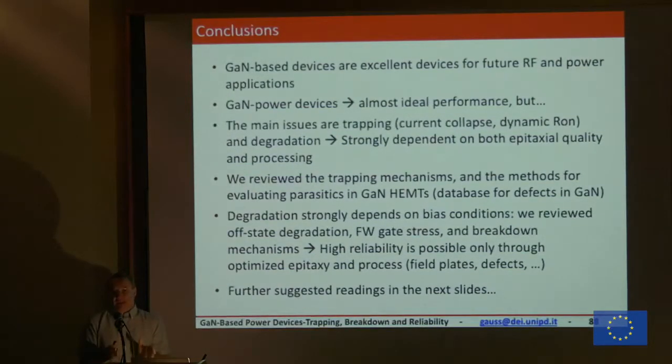At this time, we are applying the qualification procedure that we use for silicon, what we call the JEDEC procedure. So you have a certain number of devices stressed at a certain voltage, at a certain temperature, and you don't have to see any failure. But I'm not convinced that this is enough. Maybe with the defectivity of this device, with the complexity of this device, we need a more complex qualification procedure to take into account some effects or some physical mechanisms that are not present in silicon devices.